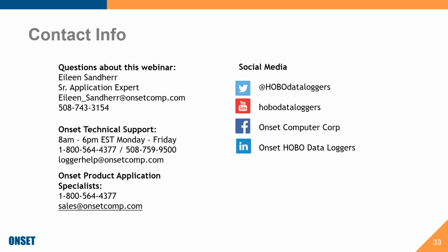But anytime you're in any area, your data loggers for temperature are going to read where they're located. Having good water flow around them is important. Sediment isn't going to typically damage any data logger. If you want to be reading the temperature of sediment, that is one thing, but you probably really want the water level, and you want to get it above that sediment. You might want to dig down a bit, and again, do a deployment with some slotted PVC and use some landscape fabric at the bottom.